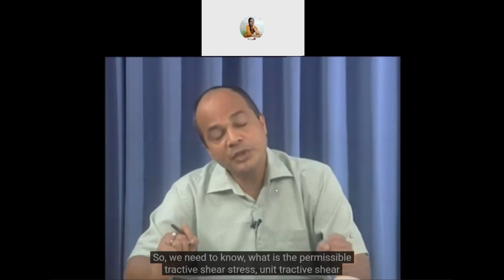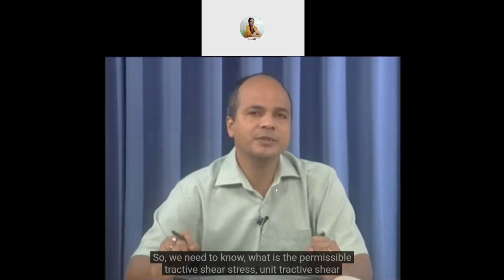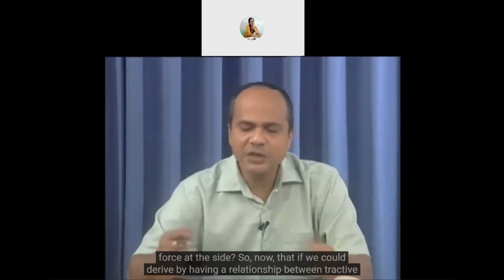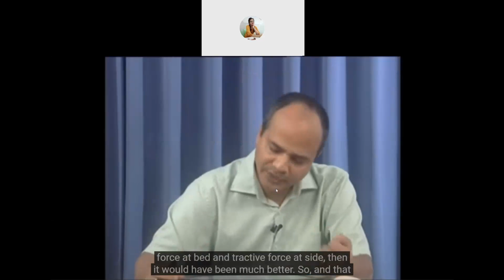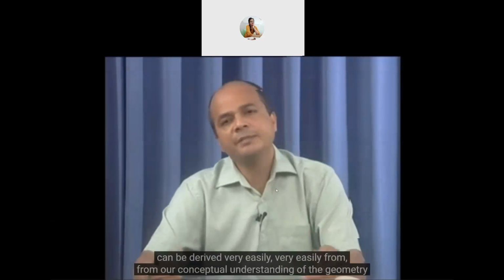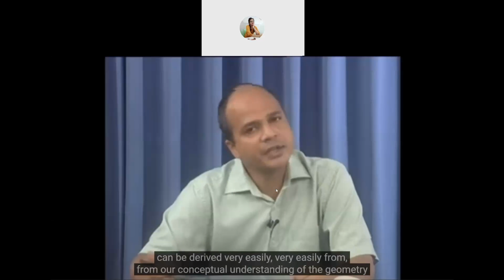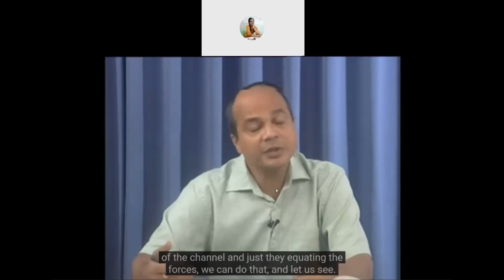So we need to know the permissible tractive shear stress, the unit tractive shear force at the side. Now, if we could derive a relationship between the tractive force at the bed and the tractive force at the side, it would be much better. That can be derived very easily from our conceptual understanding of the geometry of the channel and by equating the forces.